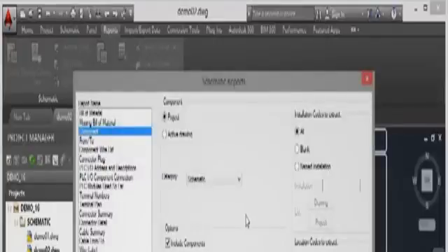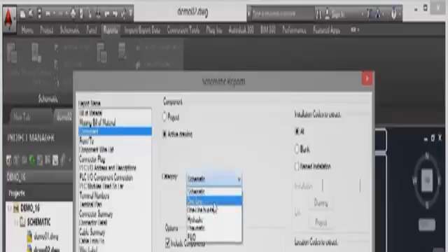Formatting, there is a lot to think about. So you can see when I go to the component report format here, I can do it via project or I can do it via active drawing. If I do it via active drawing, I can then specify a category for that component report. I can do a one-line report, a one-line bus tap report, a hydraulic, pneumatic, or P&ID. I'm just going to stick with the regular schematic components in this case. Now, I've got various options available to me, and these options change from one report format to another.